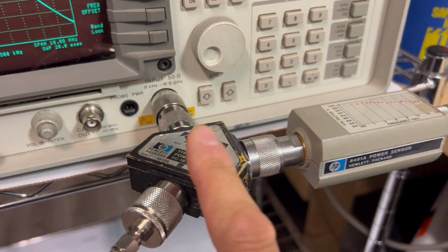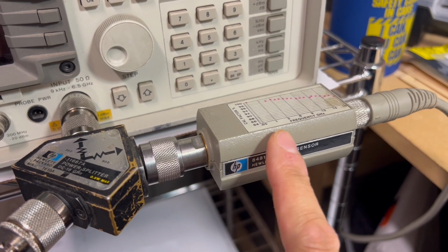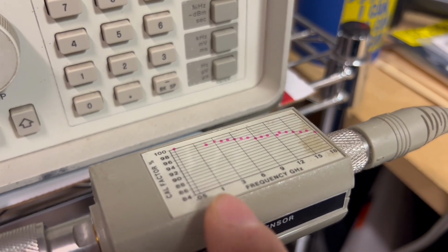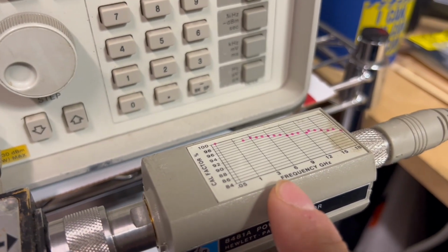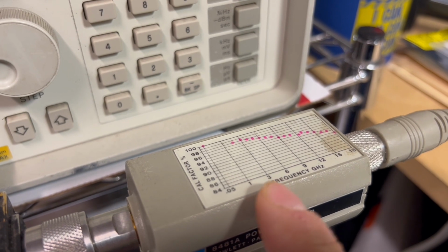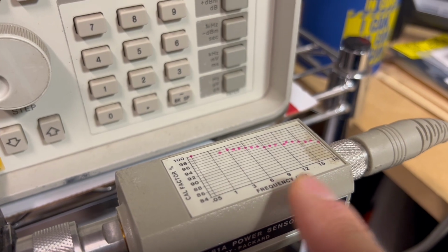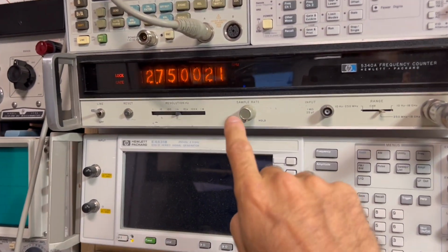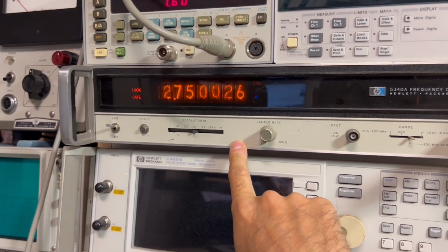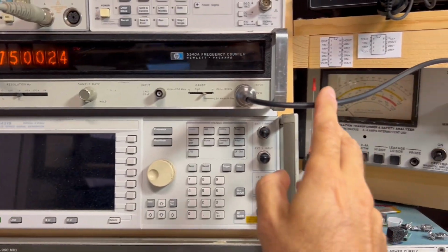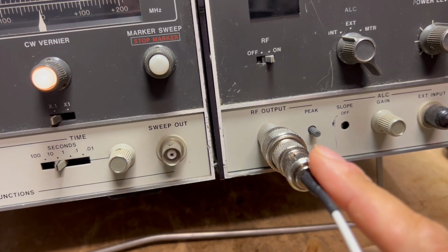And I've got my signal coming out here, going into our RF power splitter, and we're monitoring our power level here with the 8481 power sensor. And I've already made the first adjustment here, so we're starting at 2.75 gigahertz, so I'm going to use the 3 gigahertz correction factor, and then I'll adjust those as we go up the band there. Monitoring the frequency here on this microwave frequency counter. As you can see, we're set to 2.75 gigahertz, and I've got this coming off of the rear of the instrument. I can't take a reading off of the RF out.